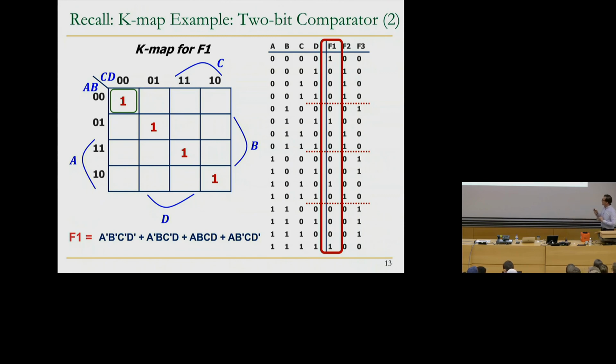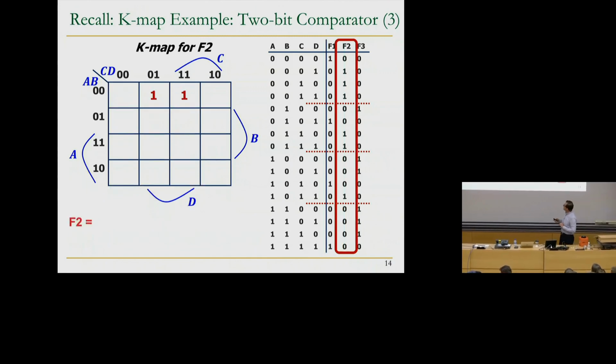Okay, that's great. But while we were doing F2, there was actually a mistake, so I'm going to correct it. Basically, we formed the K-map, but we formed it wrong. It was actually a 1 over here, whereas the 1 should have been here, right? Make sense? Basically, AB here, 1, 0, is less than 1, 1. That's why this should be a 1. This cannot be a 1 because clearly 1, 1 is equal to 1, 1, so F2 should not evaluate to 1 at that point. This is an example of why you should be very careful when translating the truth table into the K-map. You can make errors in every place, of course. Now I'm debugging my error from yesterday. So now it's debugged. This is correct.